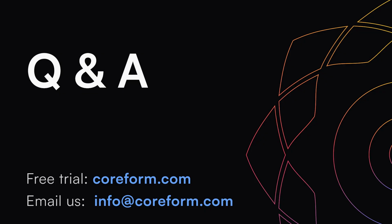What are the basis functions that we're using, and how does the basis change as the mesh is refined? Yeah, so you may be familiar that Coreform has developed a technology called U-splines, which allow us to build smooth splines on unstructured meshes. Given that the meshes we're showing today are all structured, we just use B-splines, specifically tensor product B-splines.